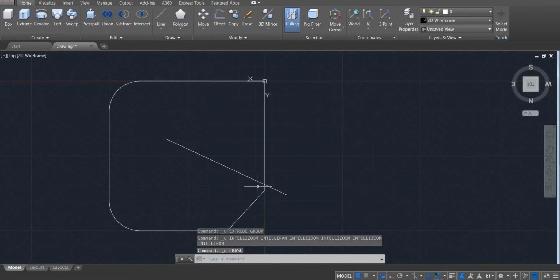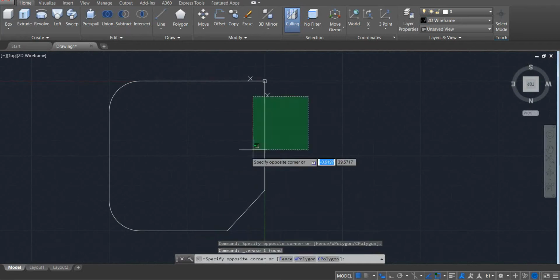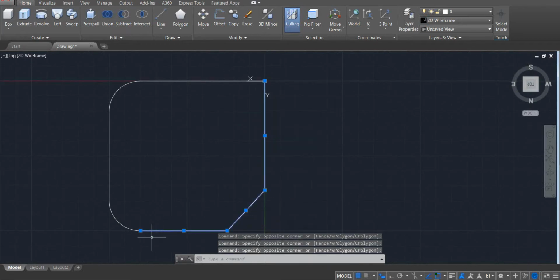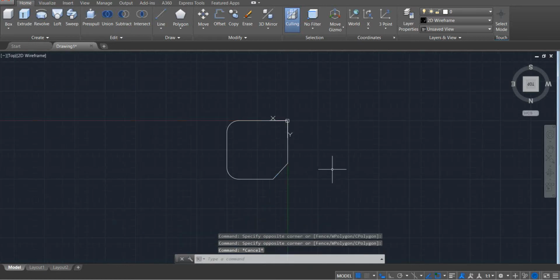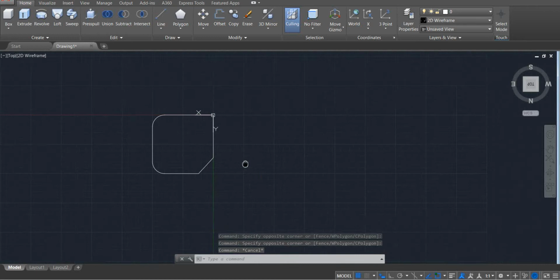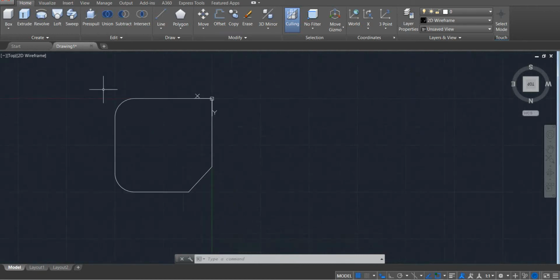This step that we missed: we dealt with these lines as separate objects. So AutoCAD extended each one of these lines as a surface. But if we joined all of them together into one single object and used the extrusion command, we're gonna end up with a standing solid object. Make sense? So how can we join them? Simply you're gonna use the join command, the same name.